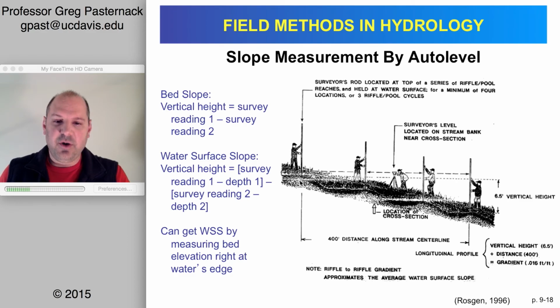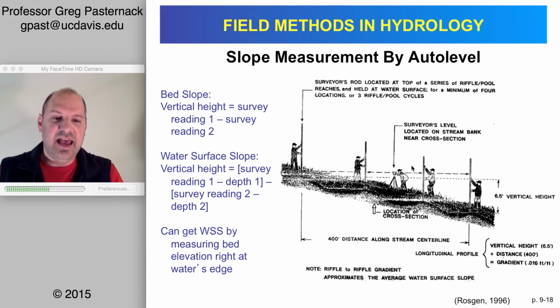So here it is, we're at the slope break at the downstream end of the crest, and then we go here, to the peak of this crest, and the peak of this one. And at each one of these locations, you make a measurement. You could also just make many, many measurements down the river and find these peaks later. It's just a question of time and your expertise. If you can quickly find these locations and see them from a single sighting, then you can just go ahead and take the shots.